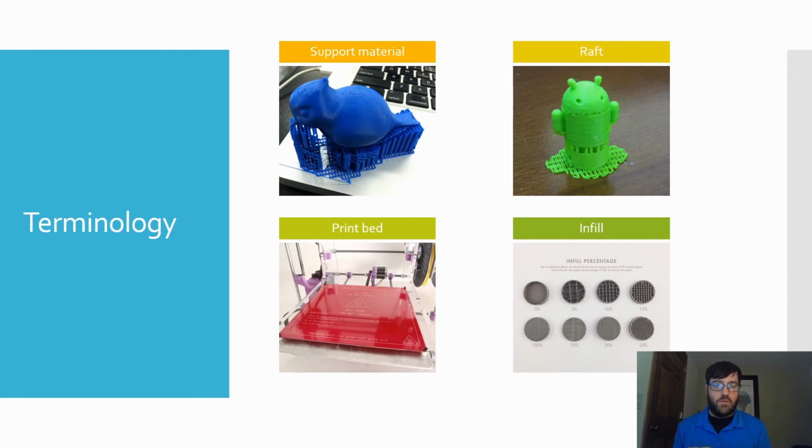You want infill to be appropriate to hold up your model, but also not be cost prohibitive. If you're using too much material, you're either spending money to have someone print it for you, or you're using your own material and you're gonna have to buy more. It's really important to find that sweet spot for infill on your designs to make sure that it's cost effective, but also maintains the stability of your print.